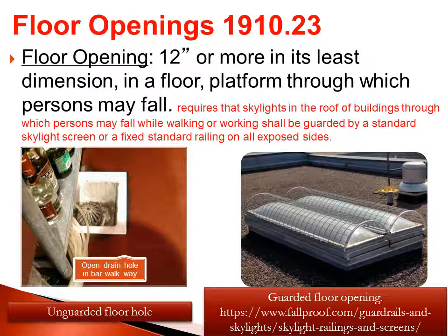Floor openings of more than 12 inches need to be guarded, not only because somebody can fall through. If it's 12 inches, your foot can fall through it. Also, you can just trip over it, as you see in the open drain in the bar walkway.